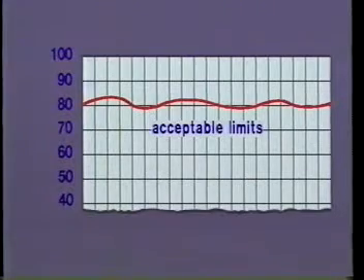Here is a continuous record of the temperature. Time has been speeded up, and the cycle we see here is many times faster than that of the actual process. Note that the variations are well within the limits of plus or minus 5 degrees. The quality of the product was excellent, and using this simplest type of controller, the on-off controller, the plant could repeat this operation day after day.